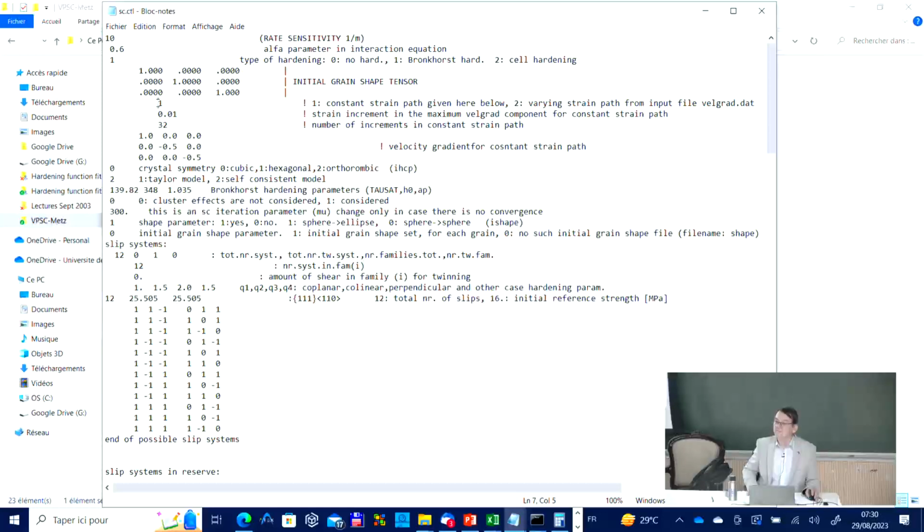Yeah? So are we considering that the aspect ratio for all the cells are the same, all the grains are the same? Yes, here we assume the same. This was the experiment. Behind there is an experiment, there is a microstructure study, there is even texture measurement on this material. So tensile testing and also texture measurement. Initial texture is measured, and I don't know if it is measured after or not, but the initial is important because we have to use the initial texture in the simulation. I will show how we use it.